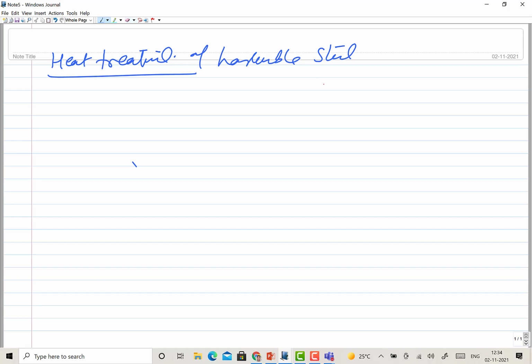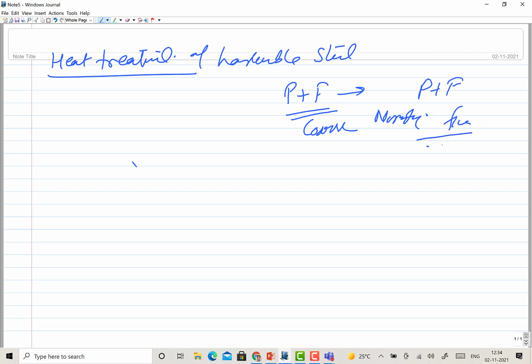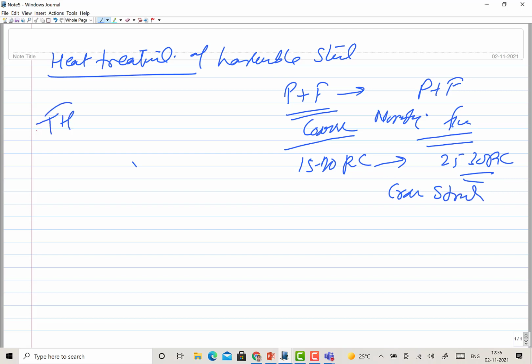No, you see, the change in hardness and strength can take place when you have ferrite and pearlite which are coarse, and during normalizing you may get fine ferrite and pearlite. Even then you will find a change in hardness from, say, 15 to 20 RC to 25 to 30 RC. My point here is, in this case there is no change of phase, there is just a grain structural change. So there is no transformation hardening.